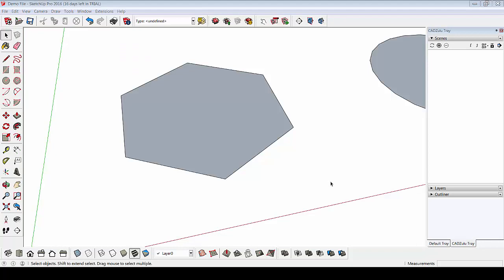Right, SketchUp's also done a lot of work in 2016 on the off-axis inferences. So improved parallel perpendicular inference display with the down arrow. So as I hover on various places, you can see if I do hold down Shift or even the down arrow, it starts doing something like this. I can inference, I can then left click, and you can see it's locked. It does actually highlight the edges, and as I start drawing again, it does show me where it's locked in.